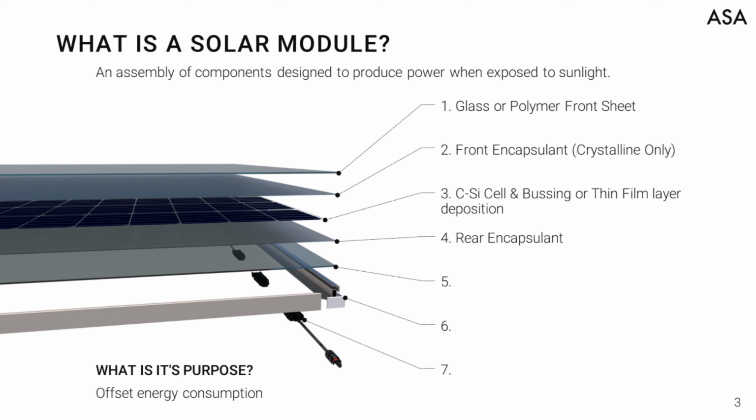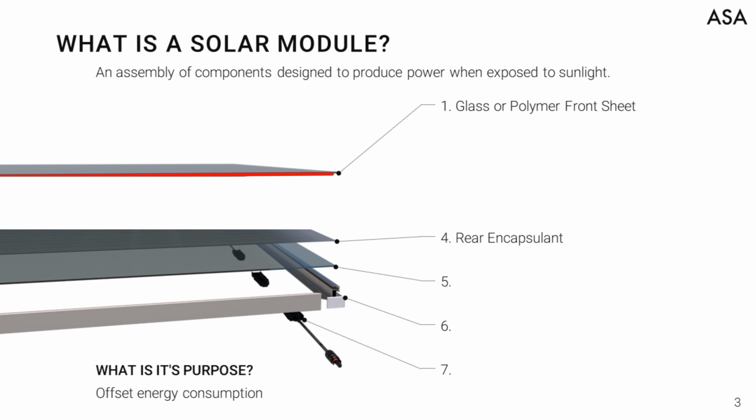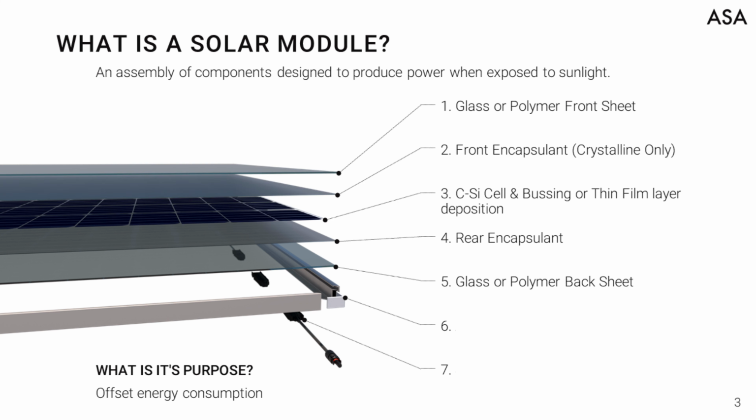Thin film solar cells typically are applied to surface 2 of a front sheet, and a single layer of encapsulant is then used to adhere a back sheet and seal the solar cells from the environment. Crystalline silicon solar cells require 2 layers of encapsulant because they are made of brittle crystalline silicon wafers. The back sheet that encloses the package can be either glass or a polymer.